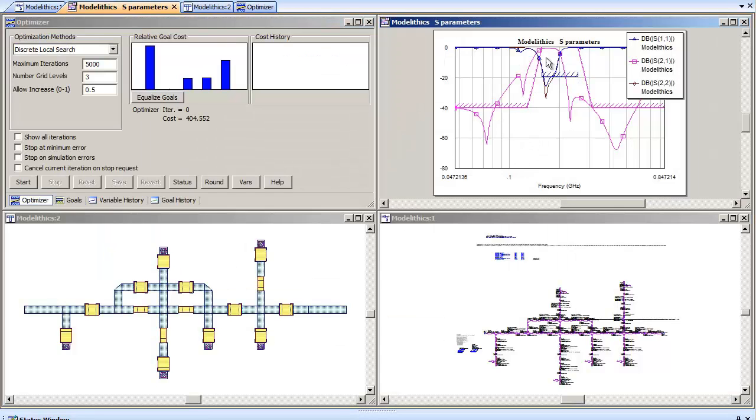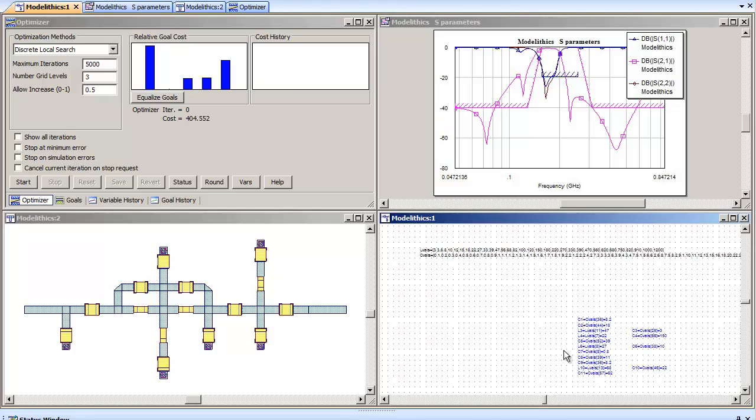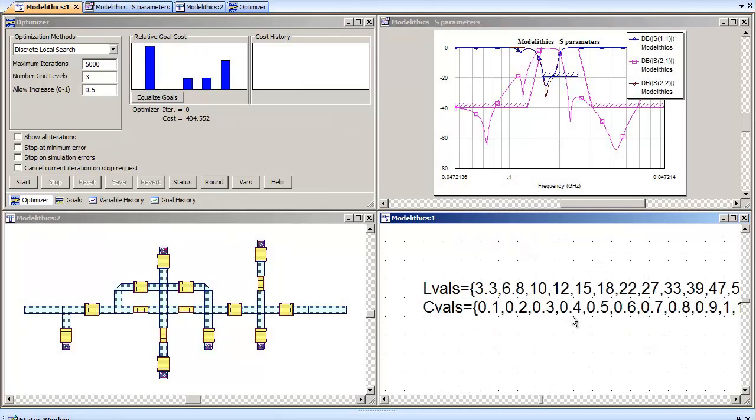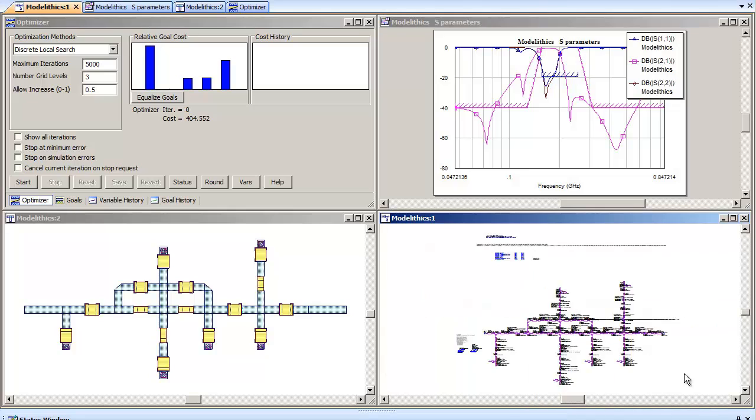And here we see our S-parameter simulation. It does not at this point look unlike the previous S-parameter simulations. However, it is more accurate in that Modelithics accounts for substrate parasitics, pad geometry, and part value variation. As you recall, the optimizations in the previous examples only optimized interconnect geometry. With Modelithics, the part values are also optimized using AWR discrete optimizations. They will go to the nearest manufacturer part value, which are recorded in these discrete equations here. We will also be optimizing to the nearest manufacturer's part. Let's begin our optimization.